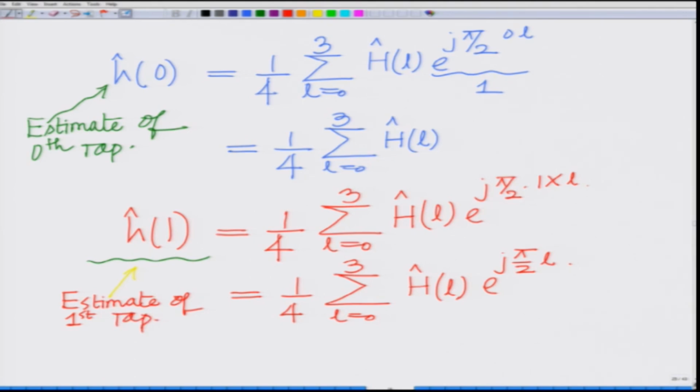So, basically what we have done is comprehensively demonstrated how to do channel estimation for an OFDM system, that is, orthogonal frequency division multiplexing system. In this module and the past modules, we first developed the model for OFDM based transmission, where we have symbols loaded into the subcarriers, that is, you perform the IDFT followed by the cyclic prefix, and transmit them over the frequency selective or intersymbol interference channel.